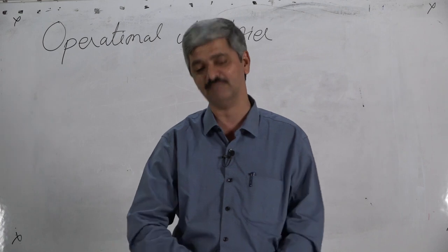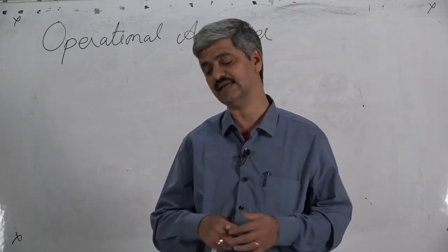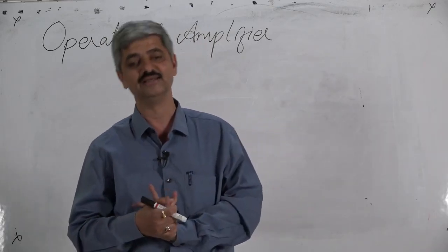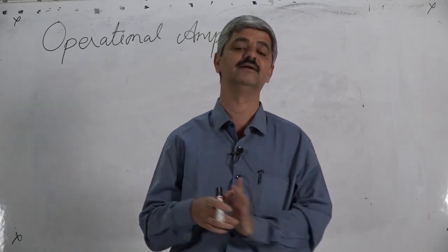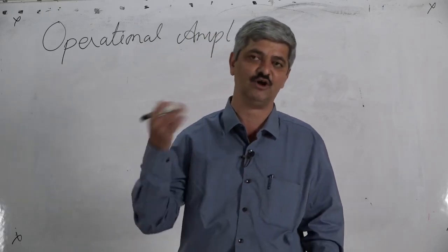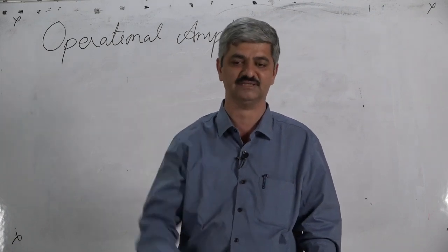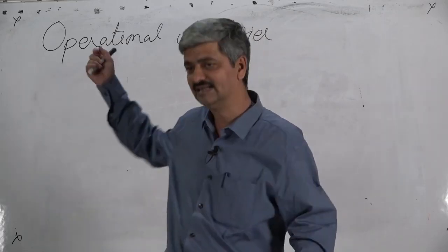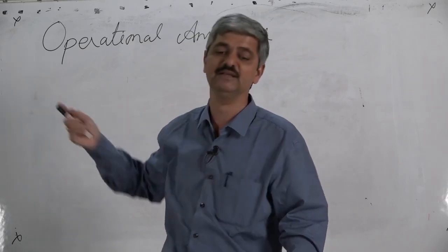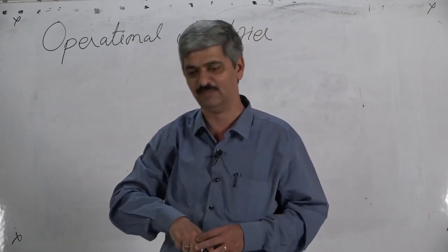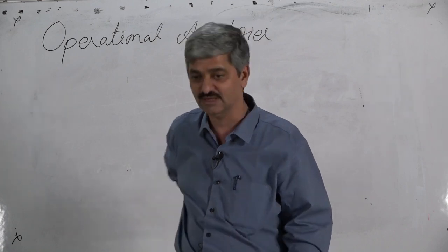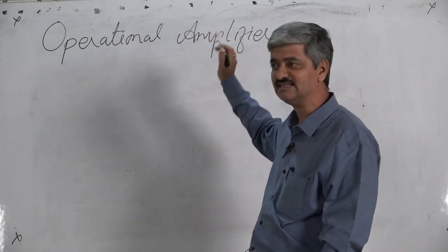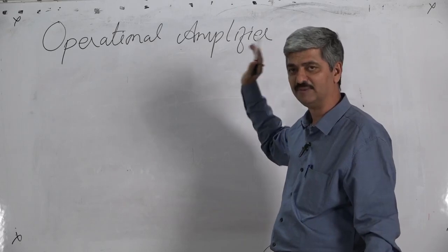And why is it called operational amplifier? Because in those days the computers which we have today were not so far developed, and even some analog computers were thought of, and people were talking about whether mathematical operations can be performed automatically by some system, and in that, addition and subtraction with real variables was thought of, that this amplifier can do. Even multiplication and division are also possible using log and antilog amplifiers, which use the non-linear characteristics of diodes. Therefore, a device which is capable of doing various mathematical operations is hence called an operational amplifier.